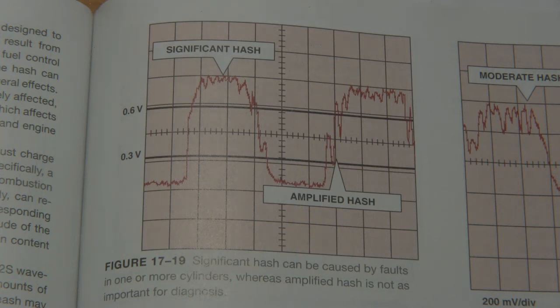Ignition misfires. Well, that one's pretty straightforward. We have an ignition event that did not take place. In that event, what is going to happen? Can the oxygen sensor see the fuel that did inject into the cylinder? It cannot. What can it see? All the unused oxygen. So momentarily, you're going to have a momentary increase in oxygen.